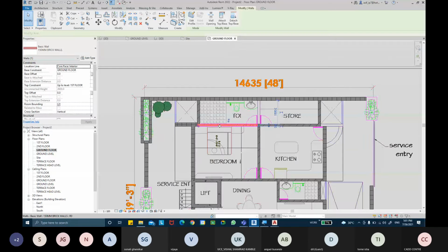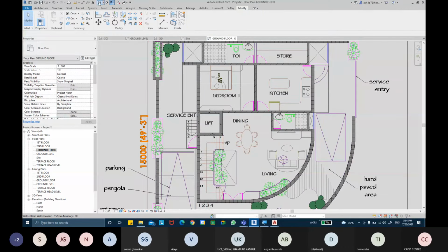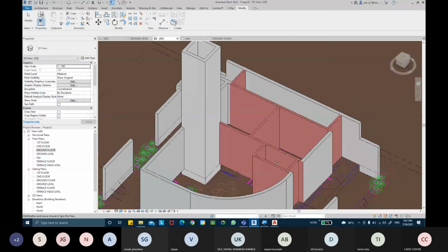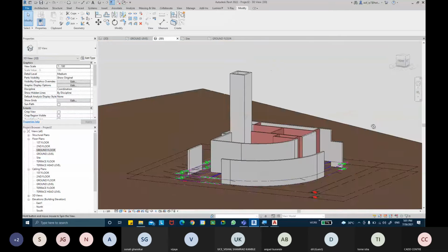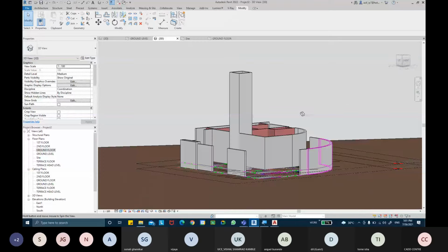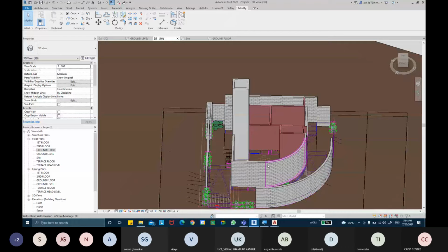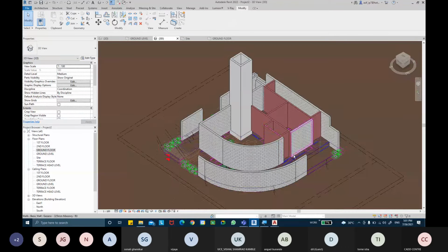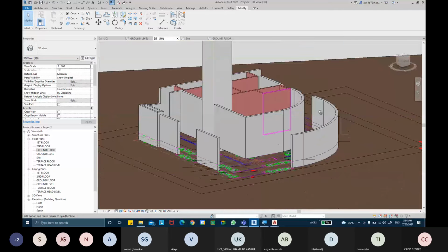All these partition walls, you can select and make sure that they are all top constrained to the first level, which they already are. Now if you look into your 3D view, you'll find that your partition walls are also ready. The quick foundation of your project gets quickly arranged. Same tools, nothing else I'm using, just showing you the method of what you should do when you start with a project. So quickly first trace all the walls.